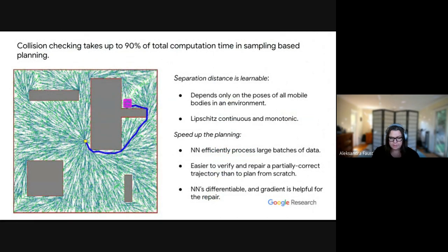Collision checking is the key component of sampling-based planning. It is the primitive operation by which we basically measure the complexity of sampling-based planning. And here is a rollout of RRT, for example. One thing that we notice is that classically we do this with computational geometry. It's expensive, it's slow, and it's 100% accurate, assuming the data being provided is accurate.